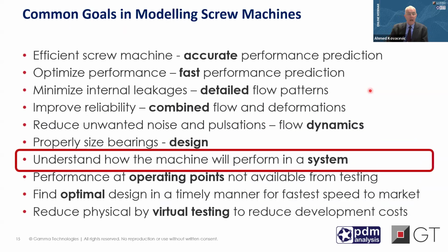Or first of all, why are we modeling these machines? Doug has mentioned a little bit about that, but what we want is accurate and fast performance prediction. We want, in some cases, to understand detailed flow patterns inside of the machine, to understand basically interaction between flow and solid deformations, because positive displacement machines work with very small clearances, and any change in temperatures or other conditions can be detrimental to the performance or reliability of these machines.